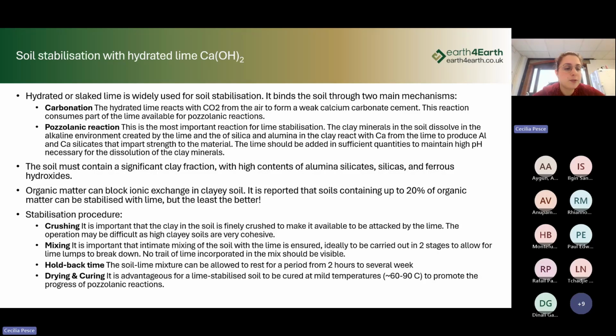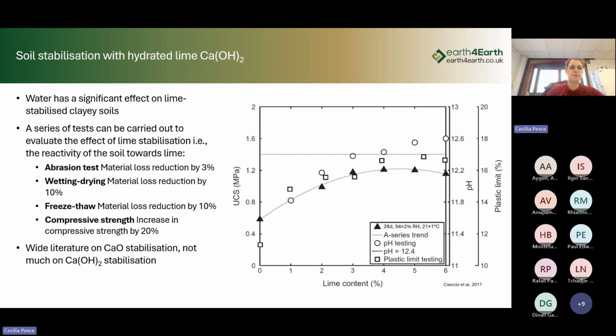Sometimes a holdback time is applied. And also the drying and curing can be advantageous. So curing at mild temperatures, around 60-90 degrees, can promote the pozzolanic reactions. So this is just to say that water has a significant effect on lime-stabilized clay soils.